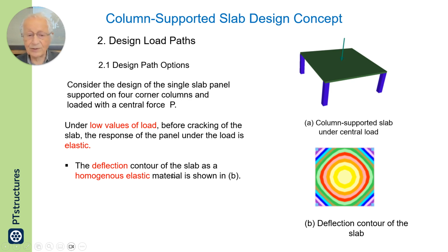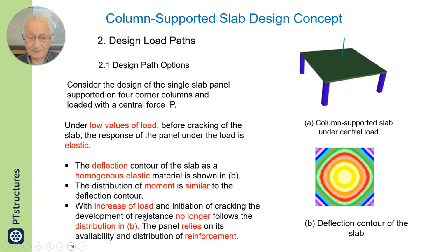The deflection contour is shown here for a homogeneous material. We assume the reinforced concrete for analysis as a homogeneous material. Now, the distribution of moment is somewhat similar to the distribution of deflection, similar in the sense that in this case the largest will be at the center.